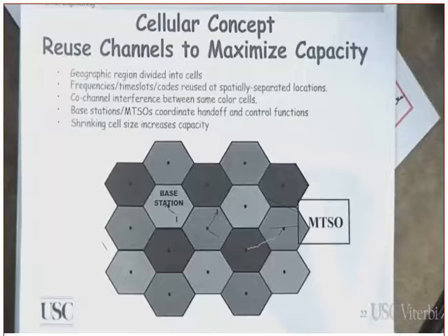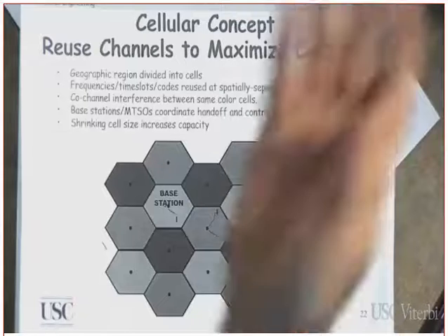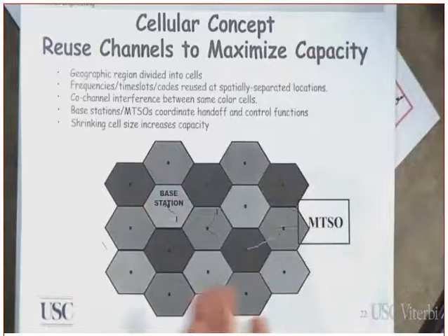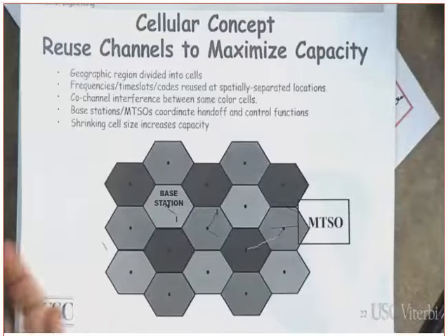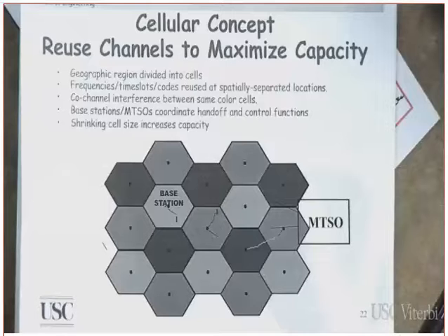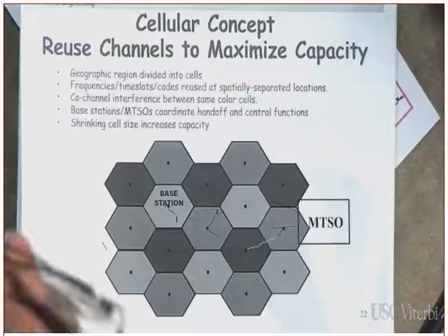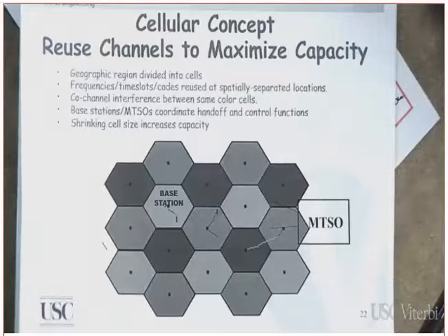However, they are orthogonal when they leave the what? The transmitters. When they reach the receiver, they are no longer orthogonal. They are going to lose their orthogonality. And if they lose their orthogonality, is that going to be a co-channel interference? That is going to be a co-channel interference because you are transmitting using the same frequency. Clear?